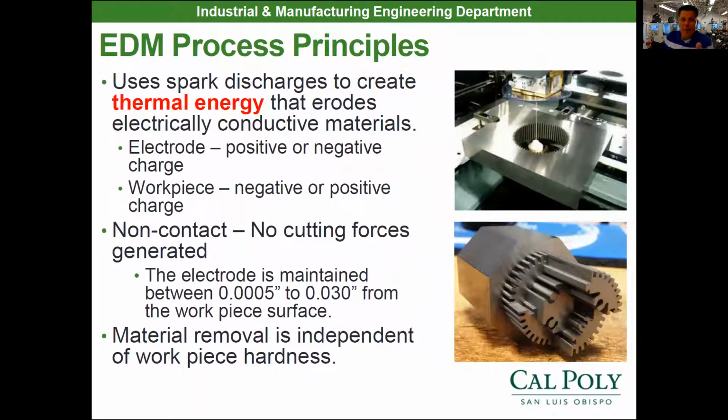But no matter what type of version we're talking about, it's using thermal energy that's going to erode that material away in the exact zone that the electrode touches the workpiece. Or there's no touching, it's getting very close to the workpiece. Because a spark is jumping across between the workpiece and the electrode, you don't have to have any contact with the workpiece. In fact, you don't have any cutting forces because a spark is actually what's removing the material. When that electrode is maintained between 1/2 thou to about 30 thou away from the workpiece,